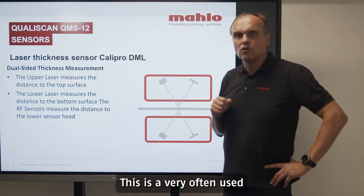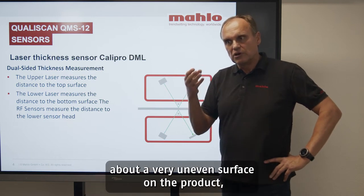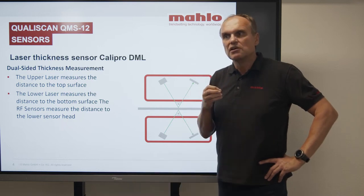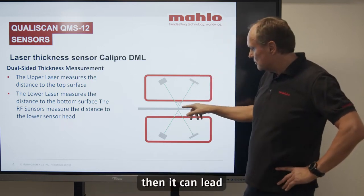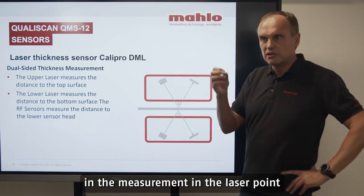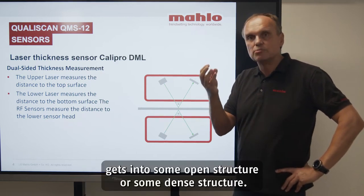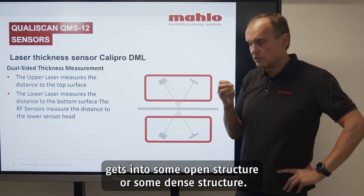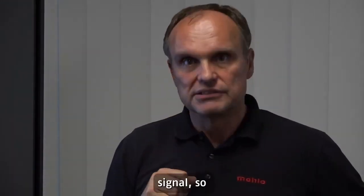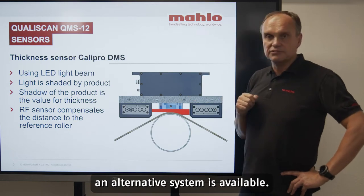This is a very often used method for nonwoven material, but when we think about a very uneven surface on the product, then it can lead to very high variations in the measurement when the laser point gets into some open structure or some dense structure. This will cause a very fluctuating signal. So an alternative system is available.